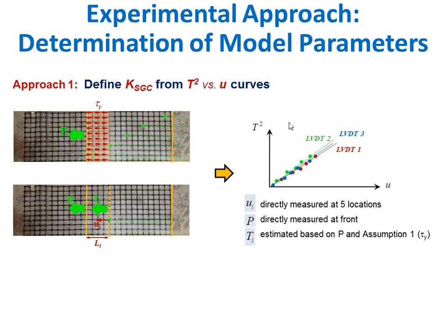If you're testing in one direction and you're under unconfined conditions, then you're going to have necking occurring, and the tensile properties that you measure under unconfined conditions will vary significantly with how wide your specimen is. Once your specimen is wide enough, then you're essentially getting rid of that, let's call it a Poisson effect, or a lateral effect.